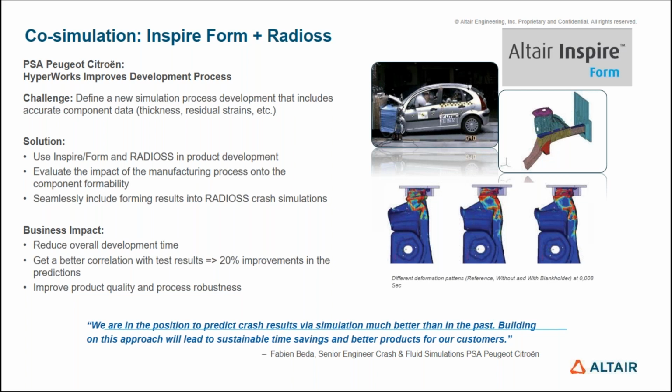That integration is possible in our interface, and you actually get a better correlation with respect to test. We have some case studies, and there are many companies using our sheet metal forming simulation, and some OEMs using Crash to Form or Inspire Form to Radioss to get better correlation.